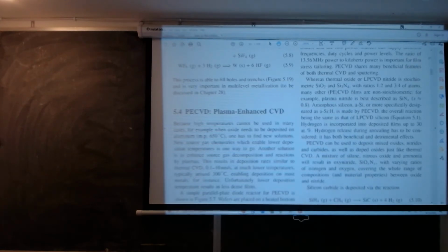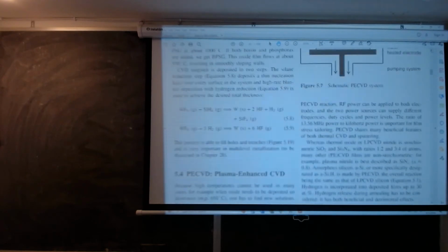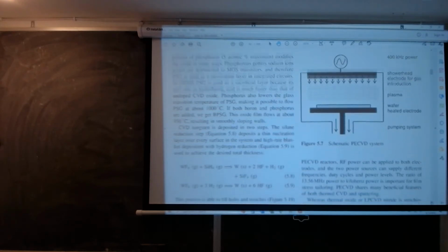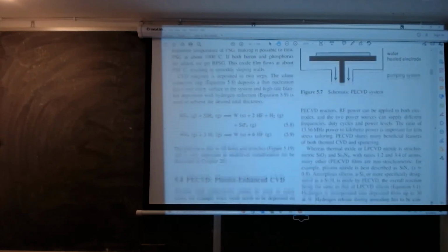This is a schematic, and you'll see what it actually looks like in the clean room video. This is called the showerhead electrode because the gases flow through it and get ionized in the form of plasma, and then the wafer's down there, and the constituents flow off to the side and back there, and that's how the material is deposited on the surface.